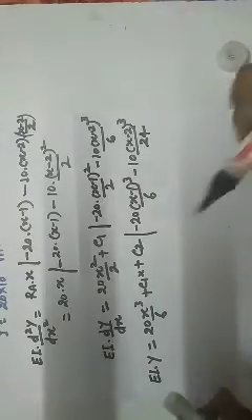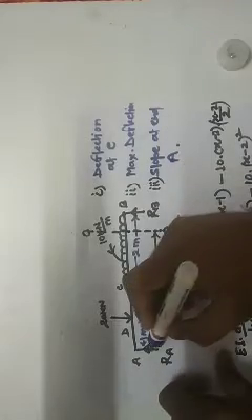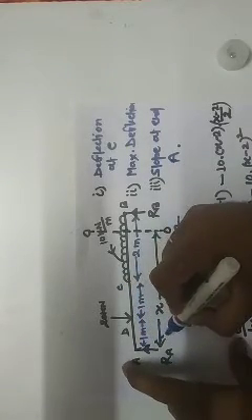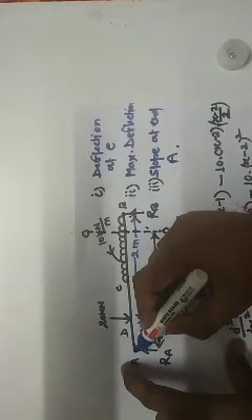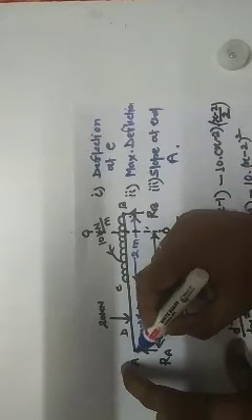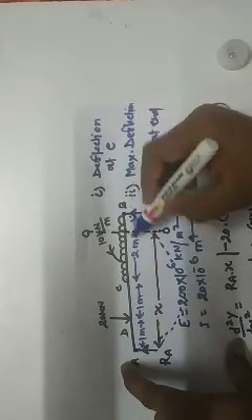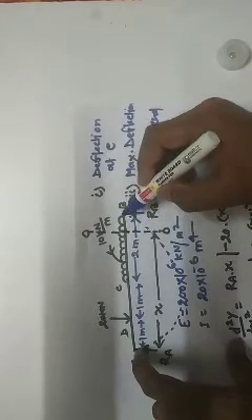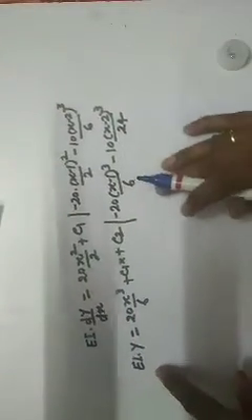Say at the end points we know, at this point, if we make a deflection of this beam, then the beam will be deflected this way, clear? Then at this point there is no deflection, because deflection starts from this point. So for x equal to 0, y is 0. For x equal to L, that is the length of the beam, that is x equal to 4, y is 0. Put these two conditions for a simply supported beam, right?